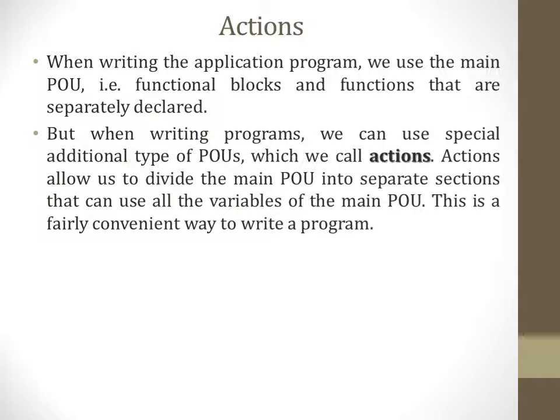But we can also use a special additional type of POU which we call actions. Actions allow us to divide the main POU into separate sections that can use all the variables of the main POU. This is a fairly convenient way to write a program, as we can see from the pictures below.